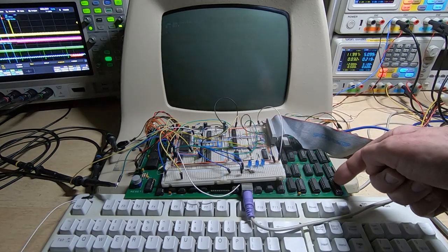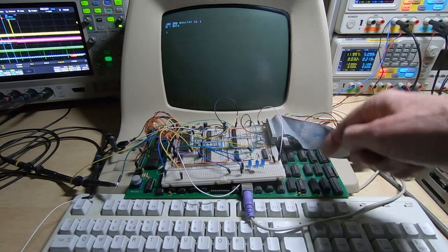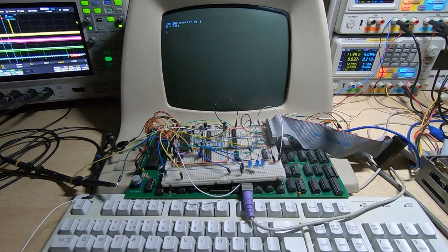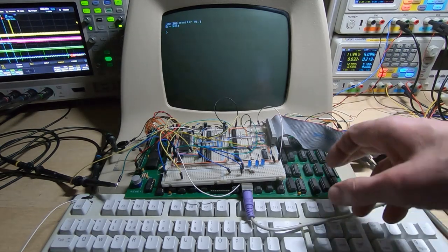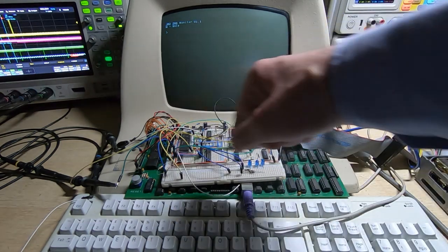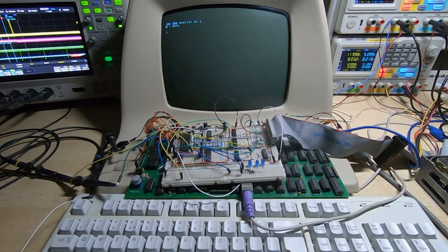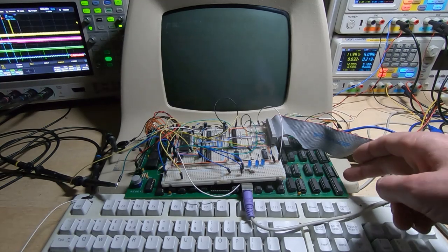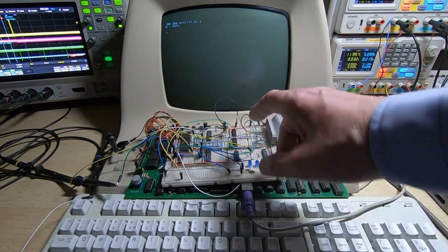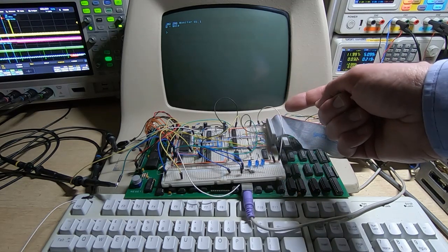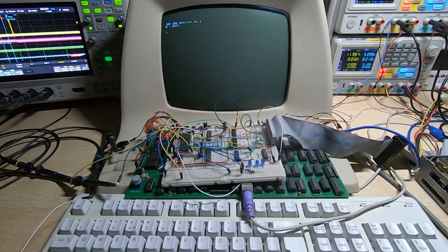This is still version 3 of the JMZ board, although I now have version 4, which I'll be swapping over to fairly soon, and they seem to work fairly well. A few additions to that, but this floppy drive interface will be on the next version of the board. I've not yet implemented DMA into this system, so I'm using programmed I/O to access this interface.